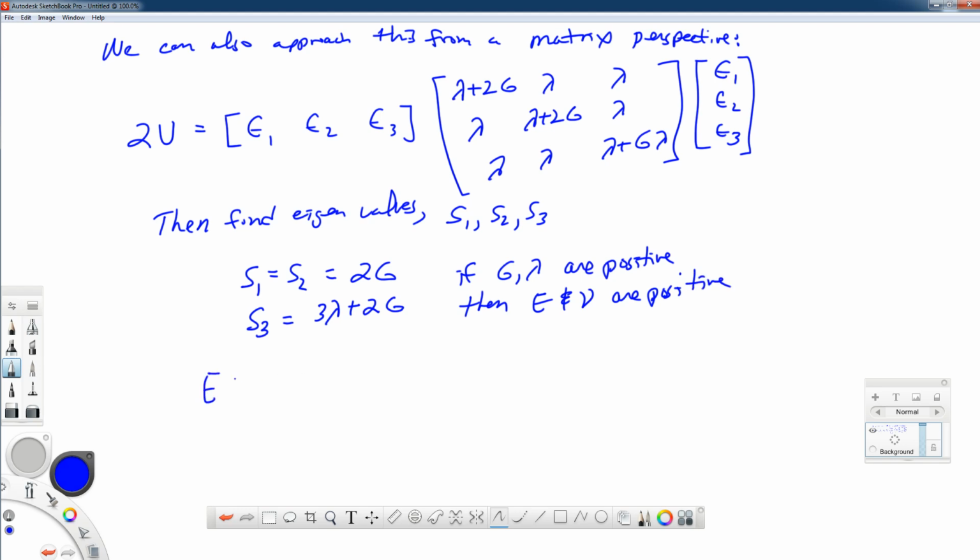And if we recall from another lecture, we actually found the usual elastic constants E and nu, modulus of elasticity and Poisson's ratio, in terms of Lamé coefficients as follows. And knowing that for engineering materials, and really any material that we know of, Poisson's ratio varies only between 0 and 1/2.